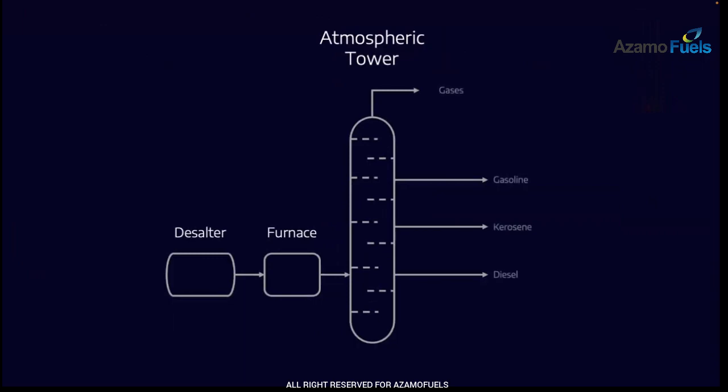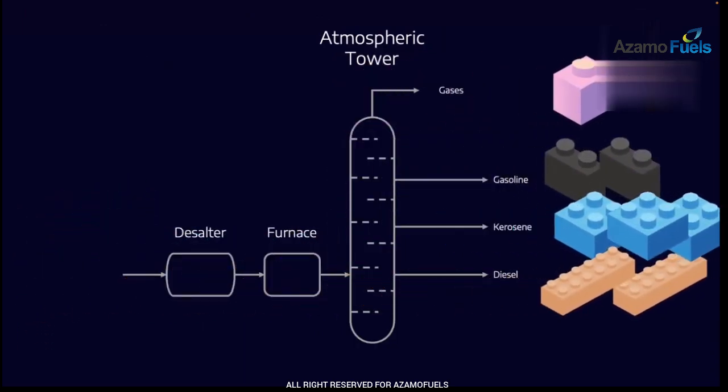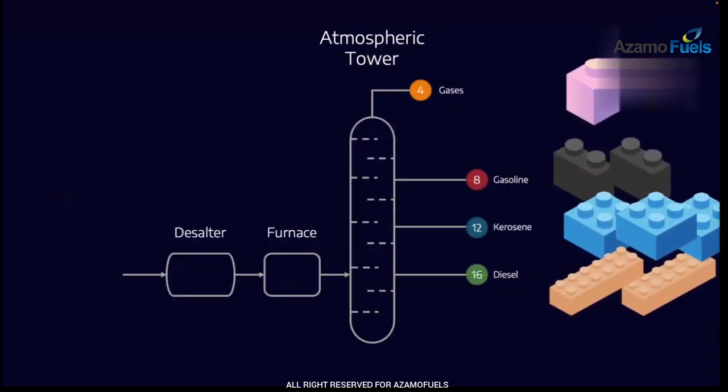If you'll remember, diesel comes out of the ground as crude oil, and the exercise of refining is to separate it out into different fractions. So if we have gases, methane only has one carbon, but methane, propane, butane, you start to increase the number of carbons. And as you increase the number of carbons, the end product gets thicker or more viscous. So if it's about 8 carbons long, that's typically gasoline or petrol. 12 carbons long is approximately kerosene, and 16 carbons long is approximately diesel.